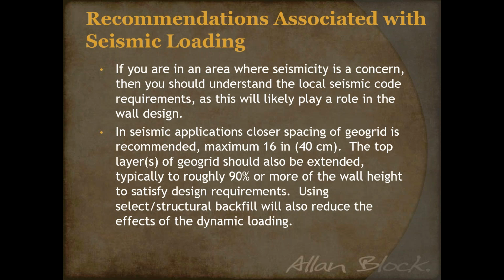If it's a high seismic zone, if you're maybe in California near a fault line, you may even want to run that on a smaller wall. It may not be the most efficient design, but certainly with a tall wall, you're always going to want to consider seismic activity. So you should check with your local code requirements through your local municipalities or also your state